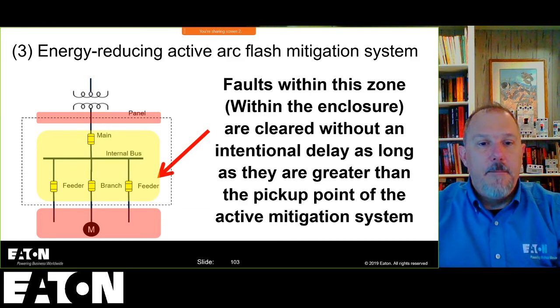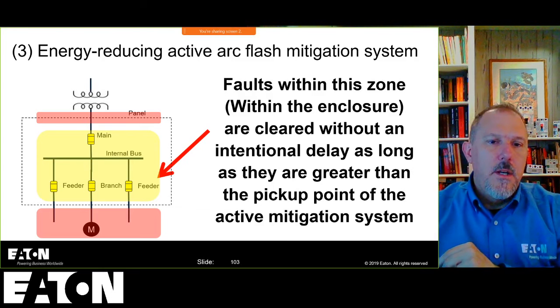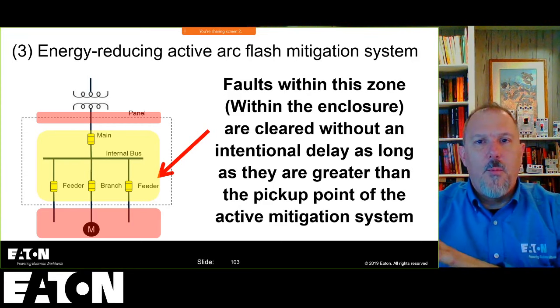And then let's take a look at the circuit breakers, right? Circuit breakers are the same deal. You have the 1200 amps or adjustable that you have to worry about and think about. We already talked about 110.16.